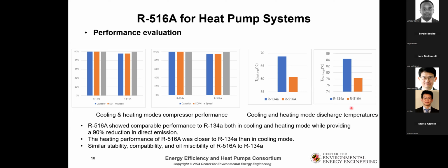In terms of discharge temperature, shown on the right side in two figures, R516A shows approximately 6 Kelvin lower discharge temperature at the cooling condition and 6 Kelvin lower at the specific heating condition compared to that of the baseline. And this makes new system design with R516A more favorable in high temperature lift conditions.